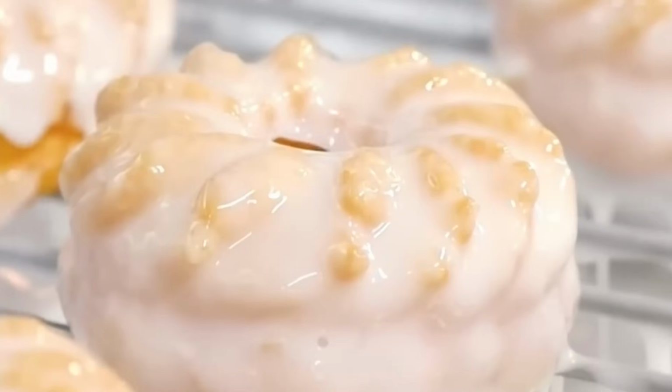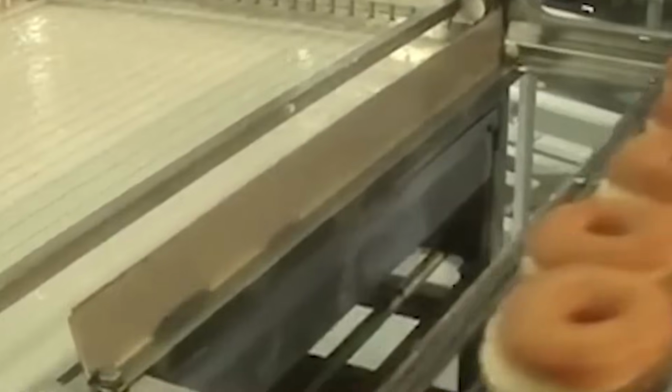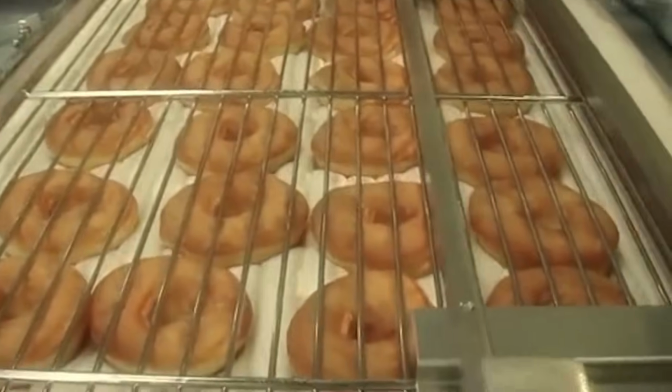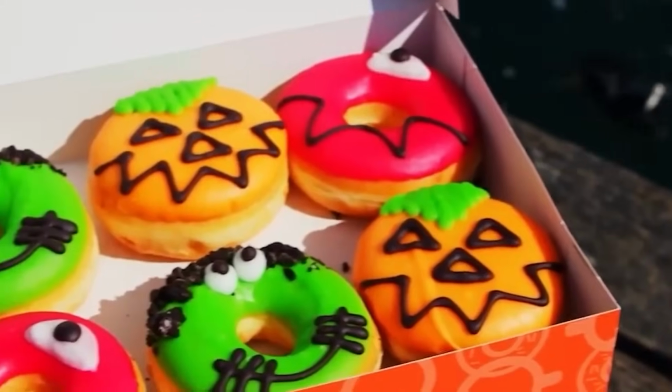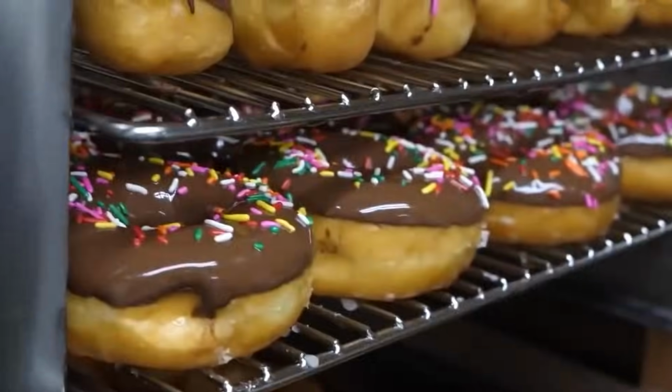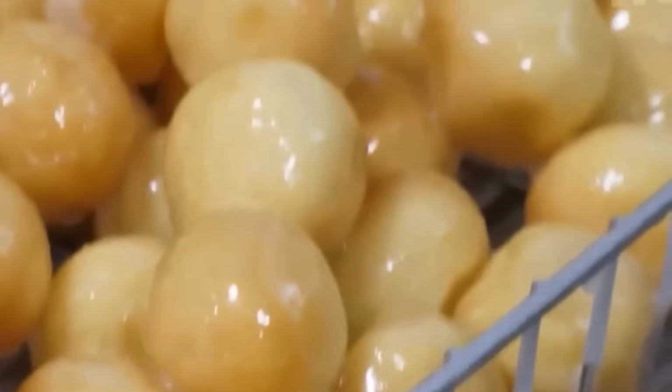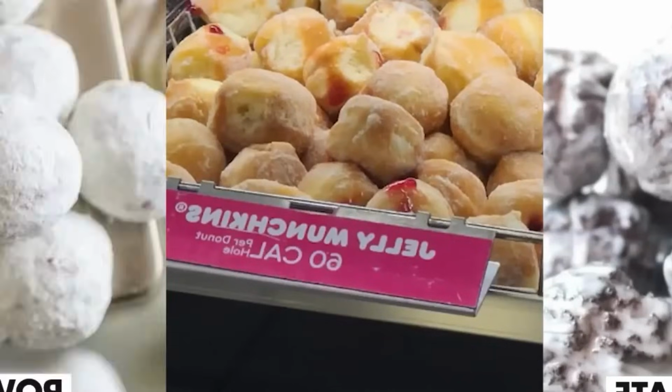Powder-coated or sugar-rolled donuts are conveyed into a rotating tumbler drum. A controlled feed of granulated or powdered sugar enters through a dosing hopper. The drum rotates at a calibrated RPM to coat donuts uniformly without damaging their structure. Fine mesh filters remove sugar clumps from the recirculation stream.